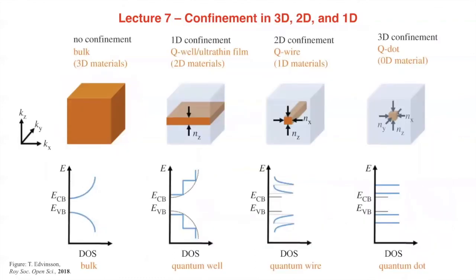Okay, so the other thing about all those nanostructures that is interesting is that the shapes of many of them are not simple. Some of them are platelets, some of them are rod-shaped crystals, and those different shapes have a big impact on the degree of confinement also. So if you take a bulk semiconductor and you say, all right, let's confine charges in that bulk semiconductor along one dimension, what you get is a platelet or a very thin crystal. And if you confine in 2 dimensions, then you get a rod or a wire. And if you confine in 3 dimensions, then you get a quantum dot or a nanocrystal.